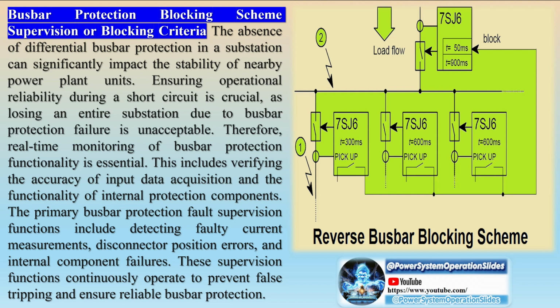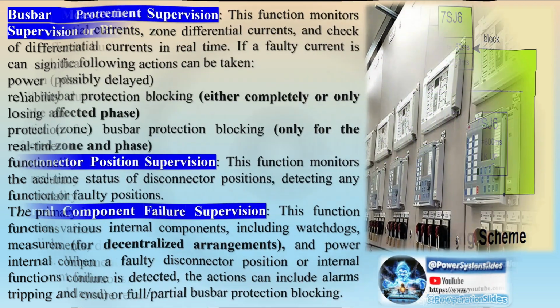The primary principle of busbar protection is the current differential principle due to its high sensitivity. Nowadays, numeric current differential relays are predominantly used because microprocessor technology enhances both performance and cost effectiveness. These relays are easily adjustable to accommodate changes in substation configurations or CT parameters.